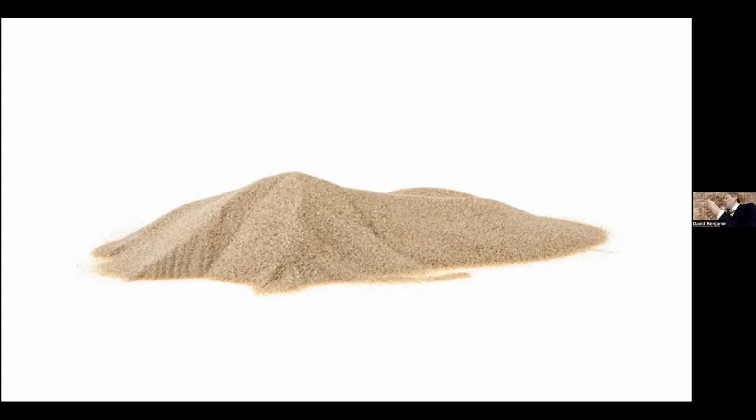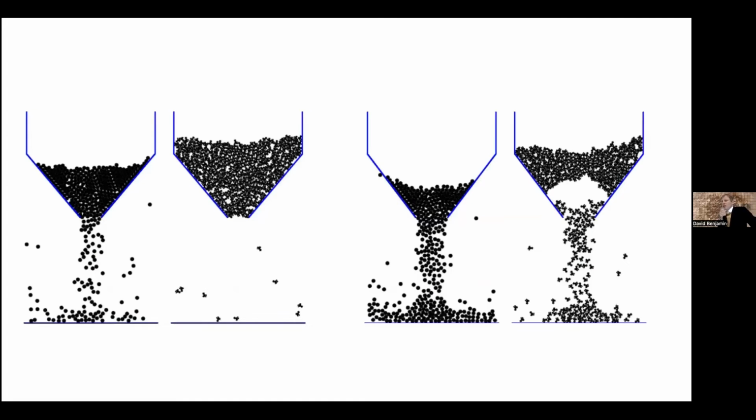If the grains of sand were more angular, then it would potentially create a steeper mound. If somehow you could create grains of sand like a tetrapod, like a forked shape of grain, then you could get even steeper mounds and do even more interesting things, as the friction of the object and the shape of the object creates certain physical properties. So this is sometimes studied in grain silos. These are just some diagrams of grain silos. And there's a whole body of research about how to avoid clogging of a grain silo, because the grains are objects, and they sometimes get clogged as they're getting poured.